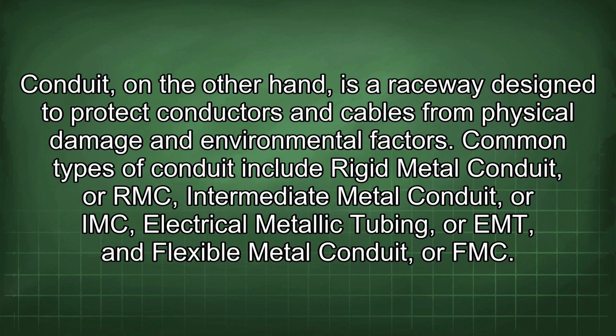Conduit, on the other hand, is a raceway designed to protect conductors and cables from physical damage and environmental factors. Common types of conduit include rigid metal conduit, or RMC, intermediate metal conduit, or IMC, electrical metallic tubing, or EMT, and flexible metal conduit, or FMC.